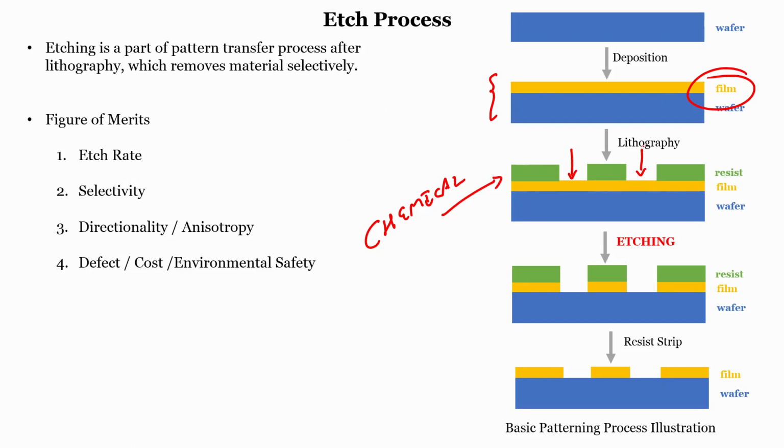When we perform lithography and dip the wafer to etch it, you will see that the film gets etched from the area which is not protected by photoresist, and in the area which was protected by photoresist, the film is still intact. After that, we have to strip off the photoresist, and stripping of the photoresist is done using acetone. We already remember stripping of photoresist using acetone. Finally, when you strip off the photoresist, you can obtain your film. This is the wet etching technique, or you can say a dry etching technique.